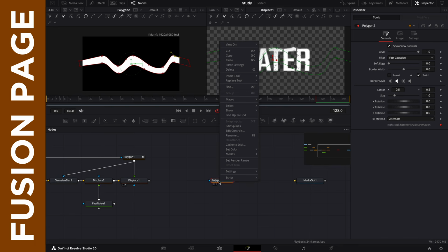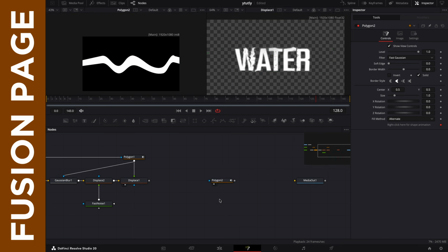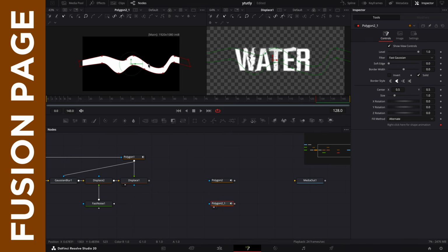Let's now make a copy of this. Right click, copy. Click on the blank part of the node grid, right click, paste. Now for this one, let's drag that to the left viewer. Let's click on this point, delete it. Let's click on this point, delete it. Let's click on this point, delete it.